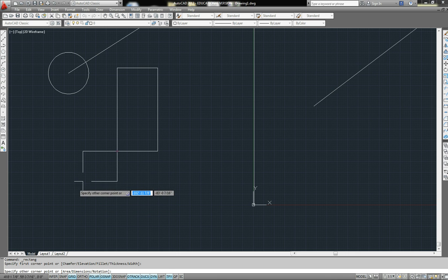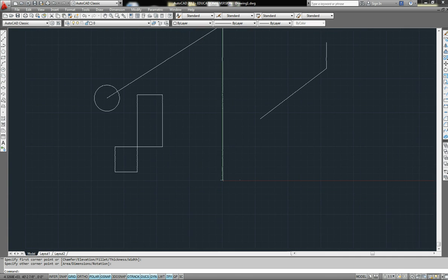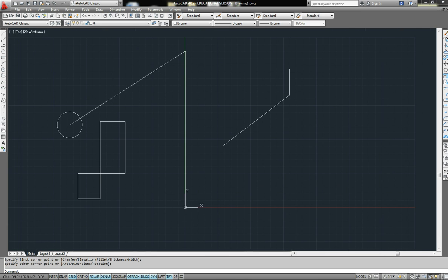Instead of typing in positive numbers for my dimensions, now if I specify negative numbers, say negative 100 by negative 100, in the same fashion that I drew this one, my rectangle will go negative 100 feet over this way, negative 100 feet down this direction. Remember, we're working in a coordinate system relative to our origin, so we can use negatives and positives to specify vertical or upwards or downwards or left and right directions relative to the XY coordinate axis.